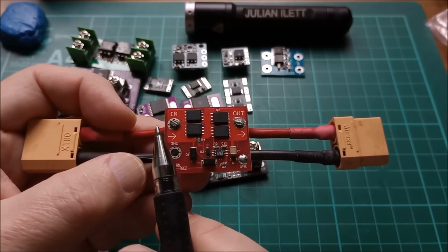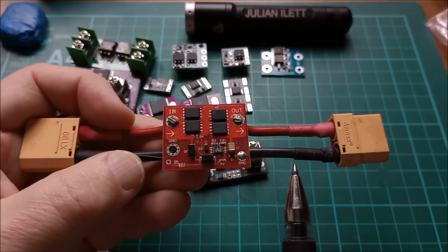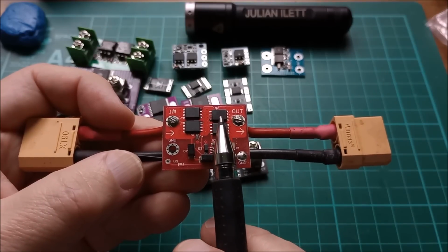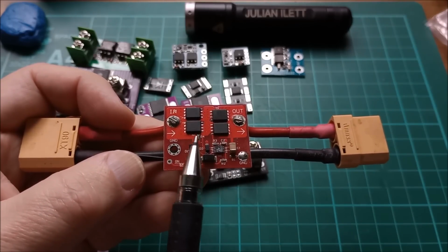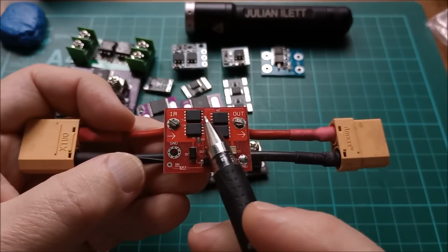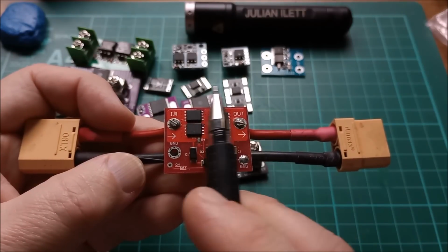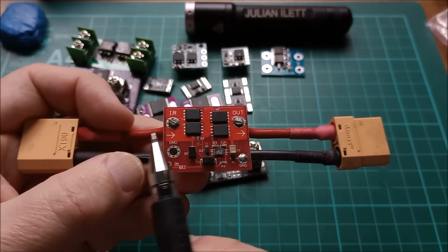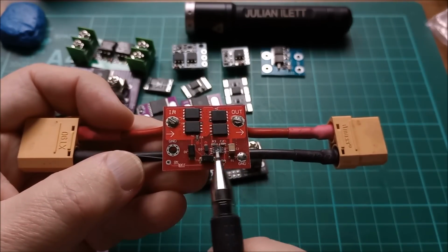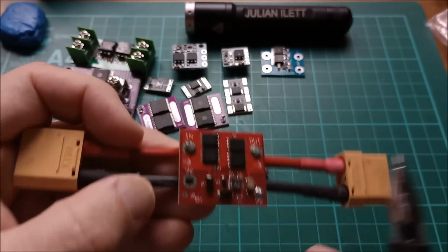So it's then nothing, it's not connected at all. And that's why this particular module, which I bought some time ago, has the ideal diode MOSFETs pointing in that direction, and then these other MOSFETs which can be used to, as I say, disconnect this high side completely. So that's just one of the applications in the datasheet of this chip.